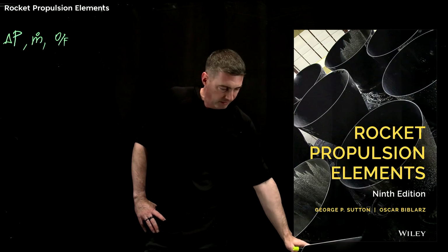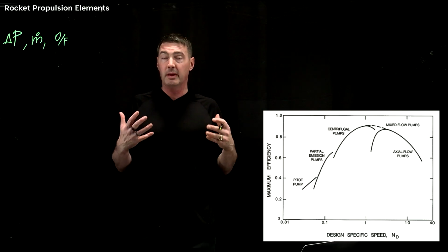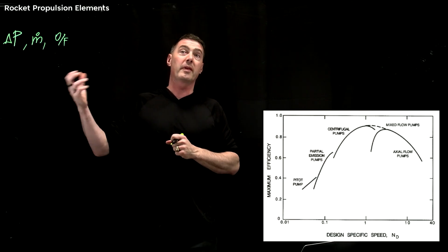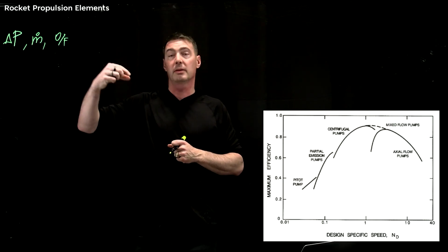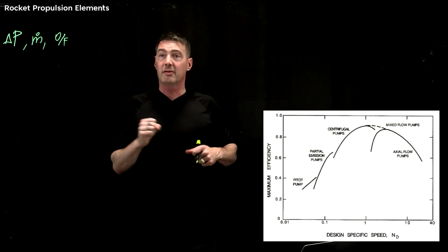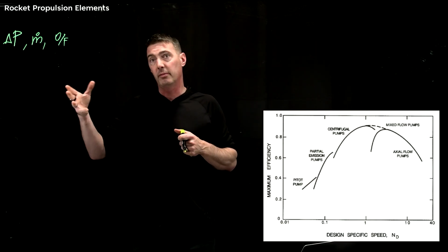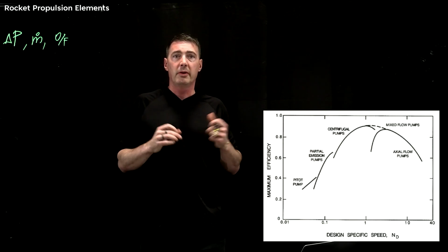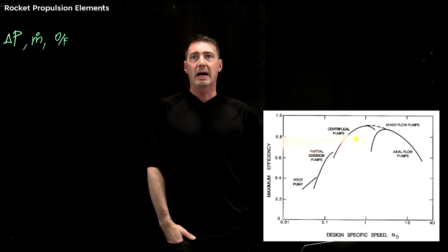Now on pumps, the first one here is sort of a picture. There's a range of pumps. The important thing about the cycles is how you're making the hot gases to drive the turbine. The turbine is attached to the pump. But now it's actually on the pump side, the liquid facing side, where the inlet of the pump is coming from your fuel tank or your aux tank. What you'll see, the main ones here, are centrifugal pumps or axial flow pumps.